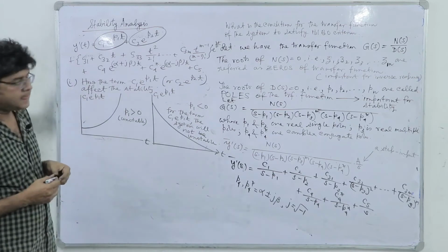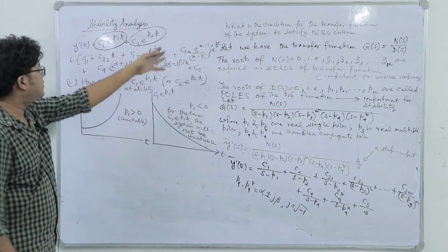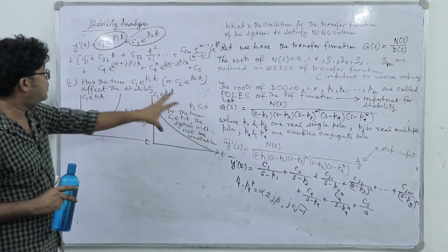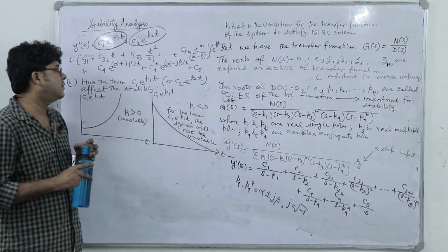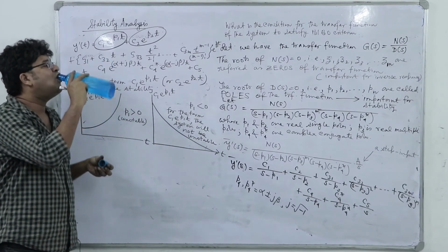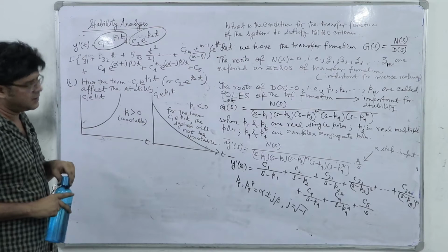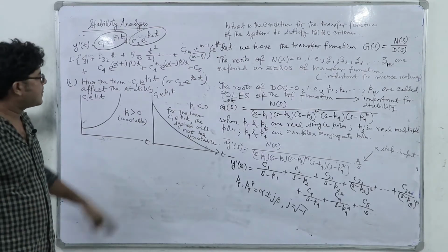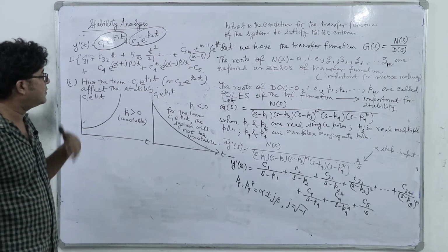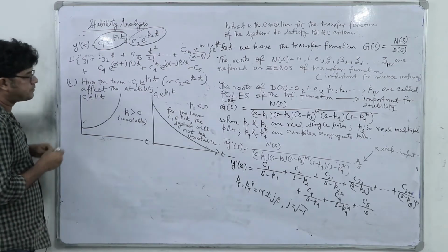It may be unstable because of the contribution of other terms as well. But if we consider the response of this first pole, which is real, positive and single, because of the contribution of that specific pole, the response is not going to be unstable.